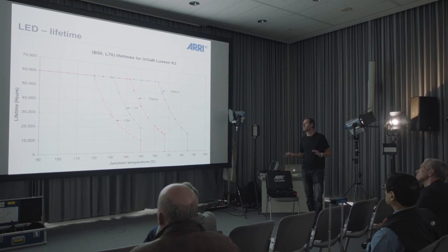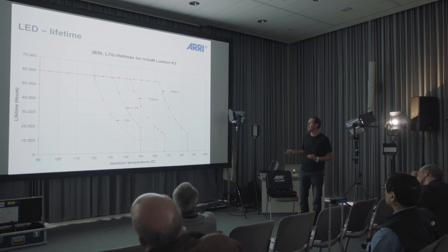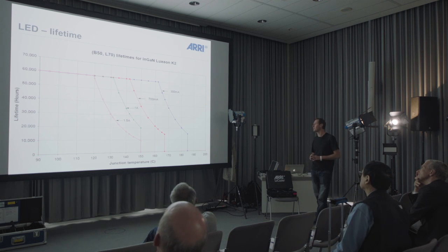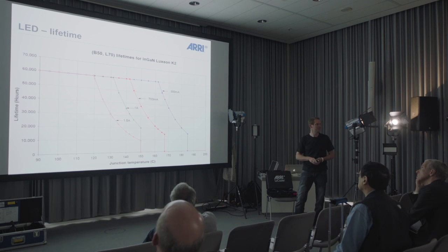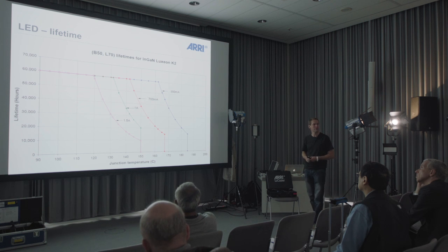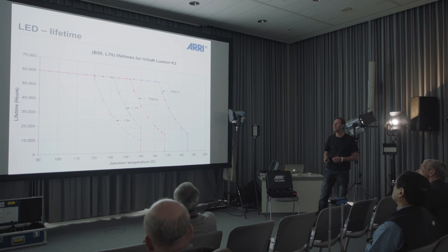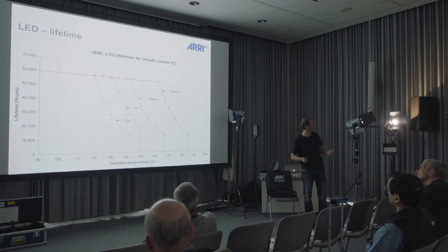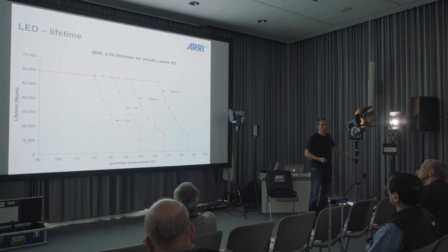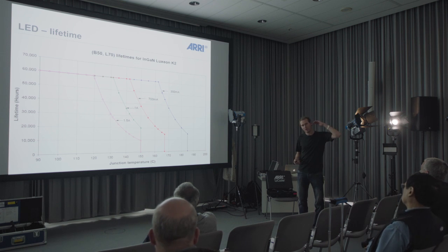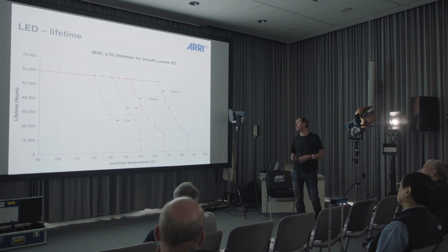So it's always better to stay a little bit more conservative and just make sure that you have a long lifetime with the LED. It's no use to have the brightest LED light for Cynic, so everybody is like, whoa, what do you have? But half a year later, all these fixtures are dimmed down. Usually when we develop the fixtures, they are planned to be in the studio for something like 10 years. And they should have a stable light output over all this lifetime.